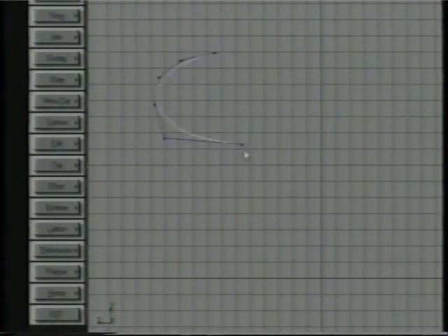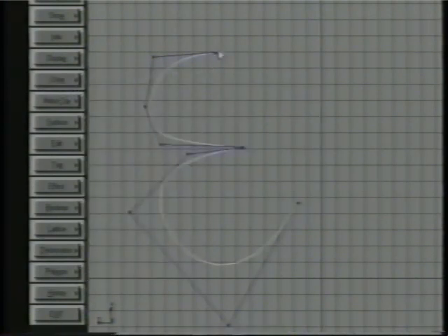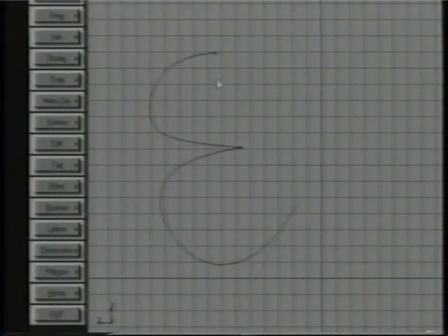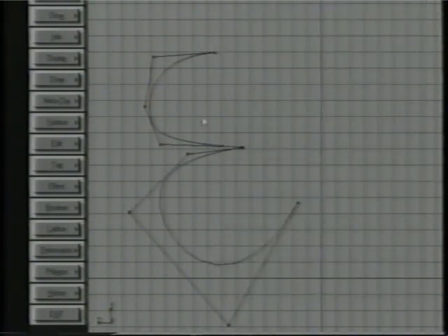And NURBS curves are the smoothest or the roundest of all the formats. By way of comparison, we can draw a B-spline over the very same points, and see how it will act. Okay, I've taken out a few points here, and I'm going to turn on unselected points and lines so you can see where those are. And I've gone in here and turned on magnet on point, so I can begin laying down these control mesh points in the very same place.